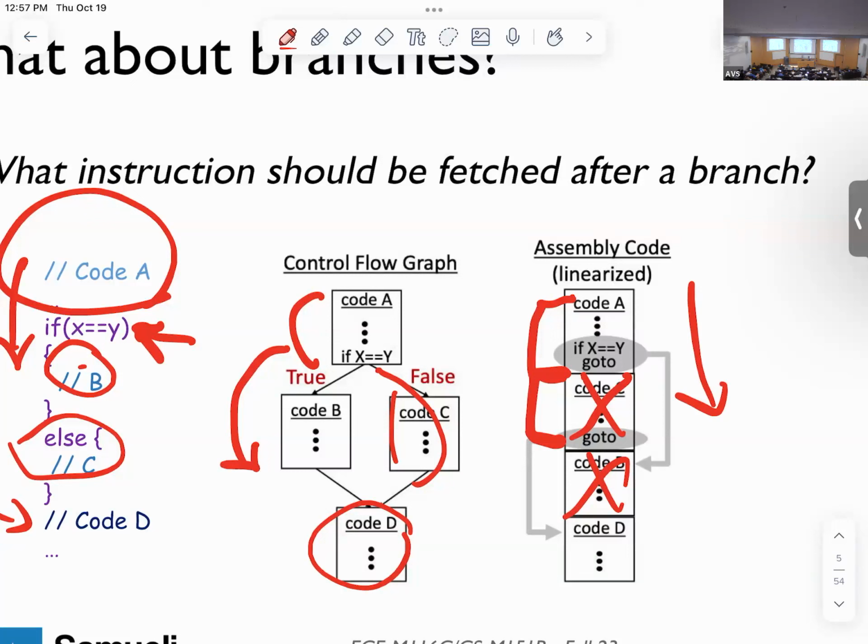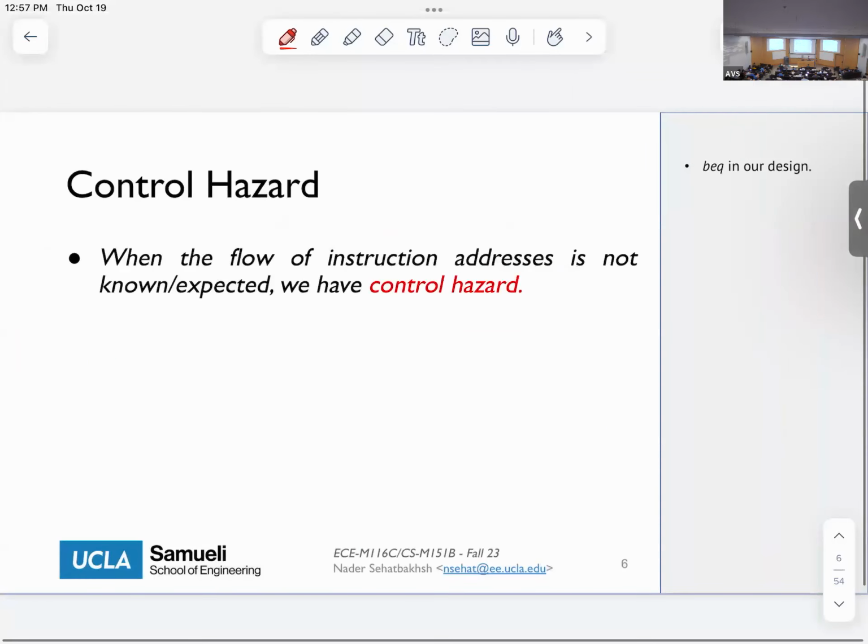So this whole idea of PC+4, PC+4 works until we have something where we need to decide to jump over, right? And we fixed this problem when we were discussing how you update your PC by PC plus offset, and branching and all those things, okay? But pipelining works in a way that you have a sequence of instructions and keep pushing things inside your pipeline, right?